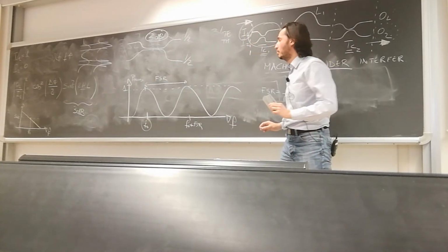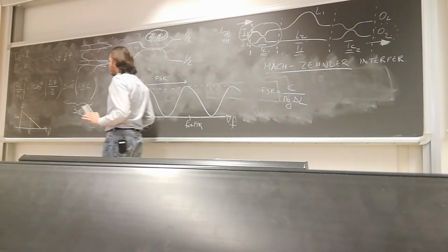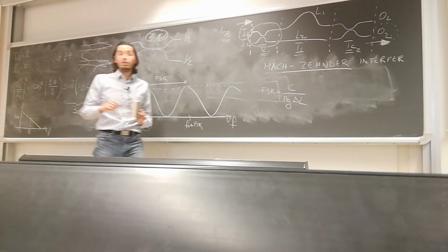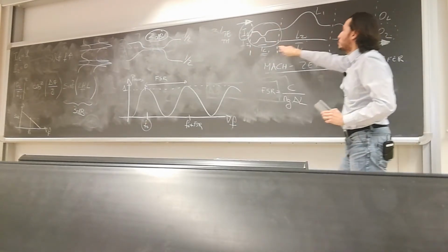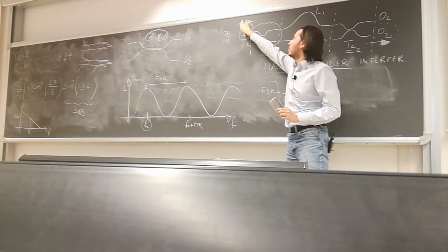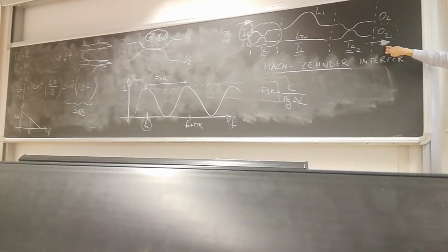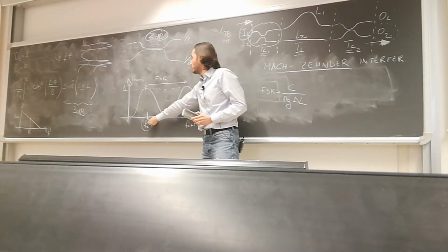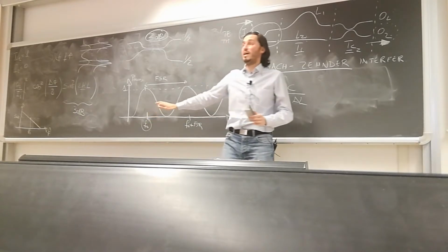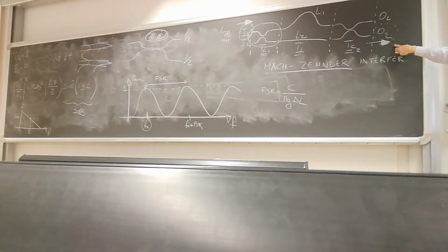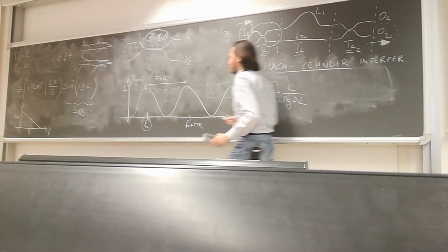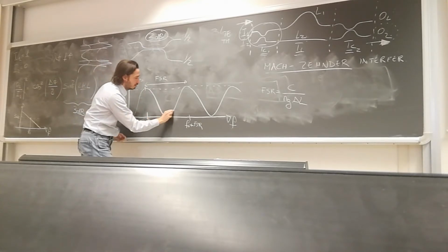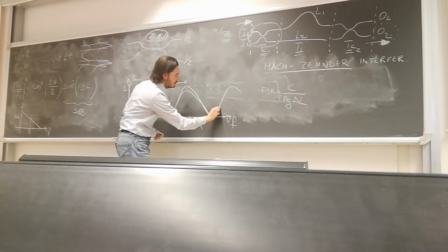Okay, no equations. That means that I move from the 3 dB condition, and the 3 dB condition is the condition that in a Mach-Zehnder interferometer allows to transfer completely the power from this port to this port. The result is that if I move from the frequency that I have optimized, I cannot expect any more unitary transmission to this port. So this means that actually what is going to happen is that here is like this, but little by little I see something like this. Goes down.